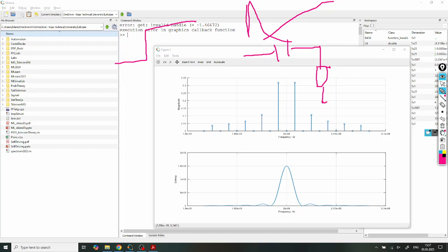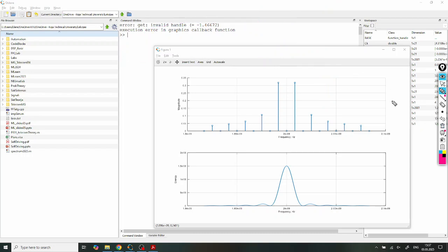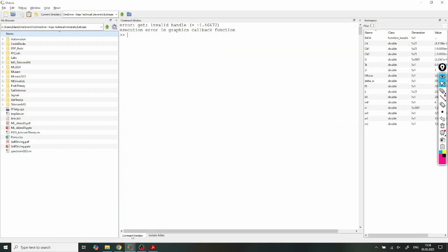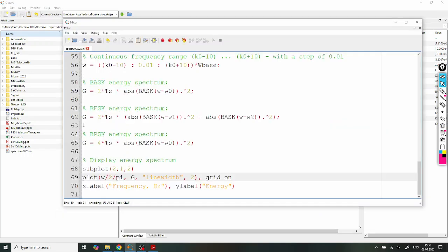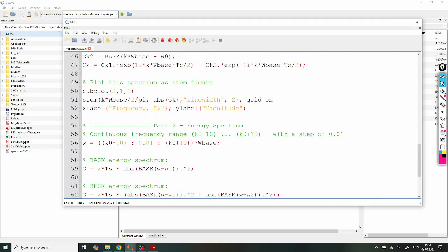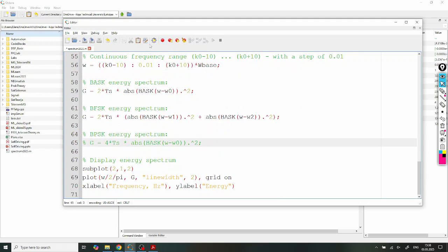And we don't want that to happen in telecom equipment, because of that, it's actually good for us that your data pulses will look like this one, not like perfect rectangles. Also, we use a filter, which inevitably is going to damage this rectangular shape, so not worth worrying about in the first place. Okay, now if you change the modulation type, let's say I will now want to see frequency shift keying, BFSK, some plot, yes, everything seems to be fine.